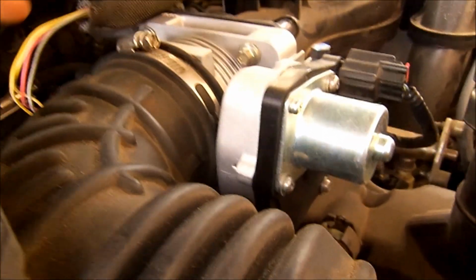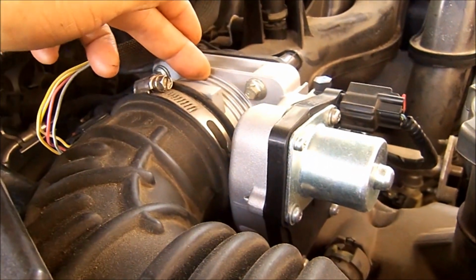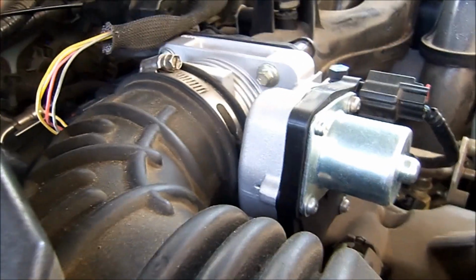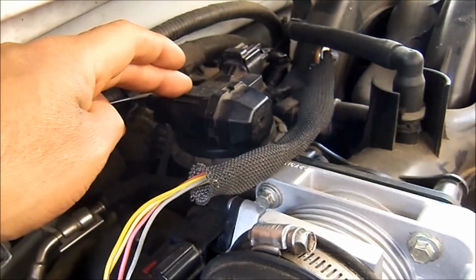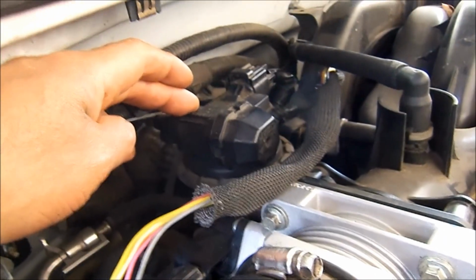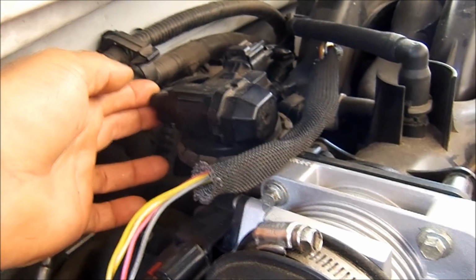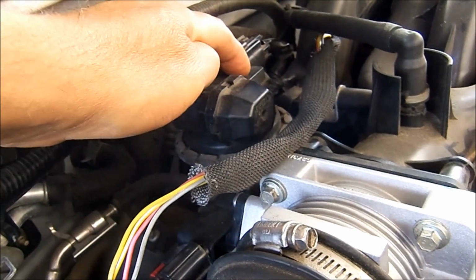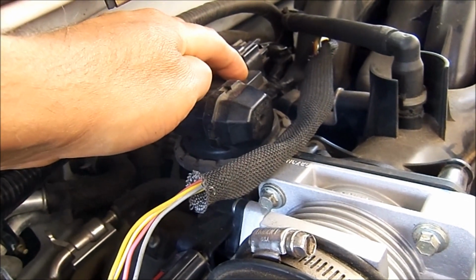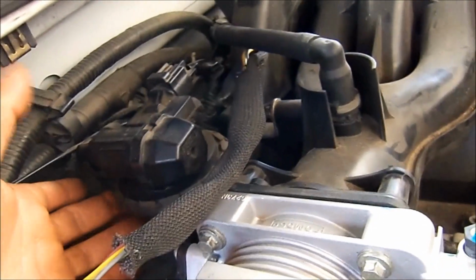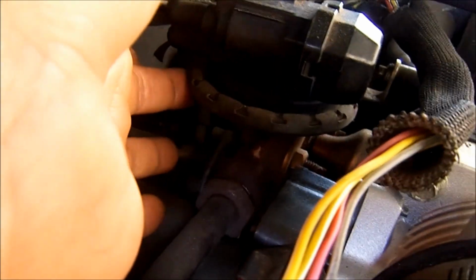Now you see here that the throttle actuator is brand new. It's from Ford. It's been replaced. And this is the EGR sensor module that I was talking to you about. You have the EGR solenoid here, the 2 vacuum ports going into here, and the DPFE sensor, which is also used as a MAP sensor. And the EGR valve itself is up underneath here.